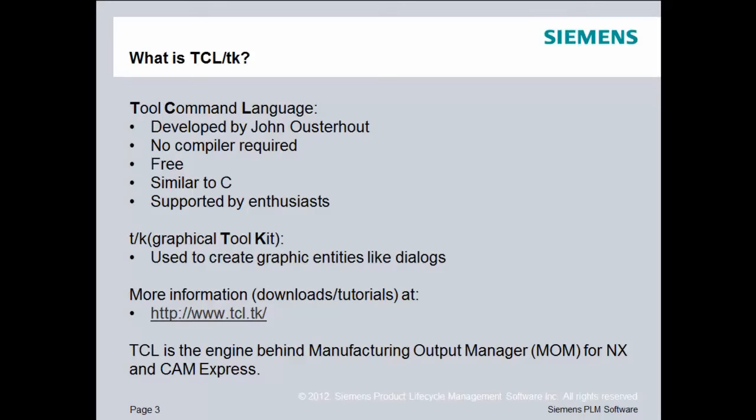How does TCL work with PostBuilder? Well, TCL is the engine behind the Manufacturing Output Manager, or MOM for short, for both NX and CAM Express. So if you're outputting anything from NX or CAM Express, you're using the Manufacturing Output Manager. And if you're using the Manufacturing Output Manager, you're also using TCL.